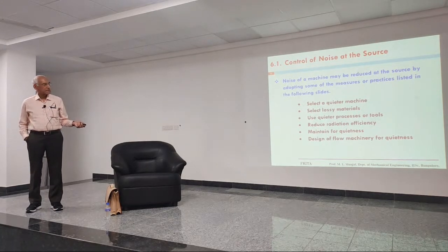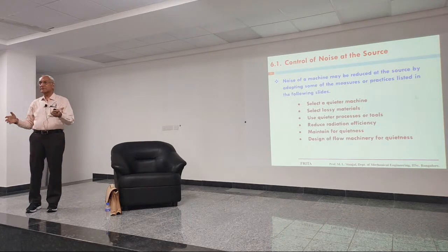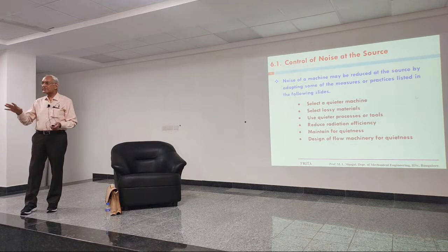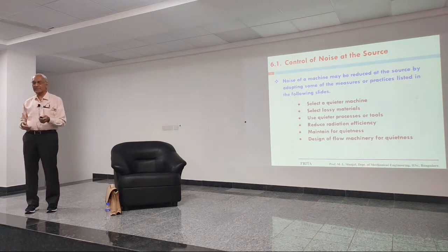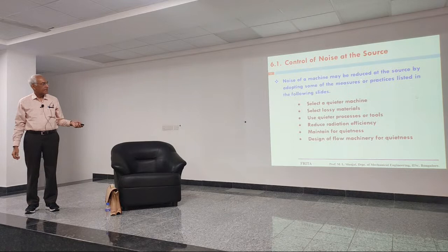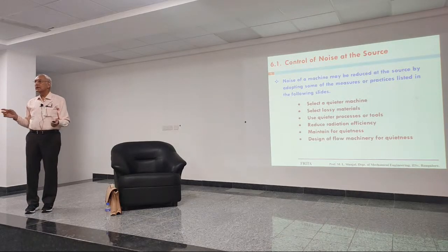Then reduce radiation efficiency. That means for, say, a plate or something which is vibrating, can I design or remodel it in such a way that for the same vibration, noise is less, because that ratio is called radiation efficiency. Then maintain for quietness.